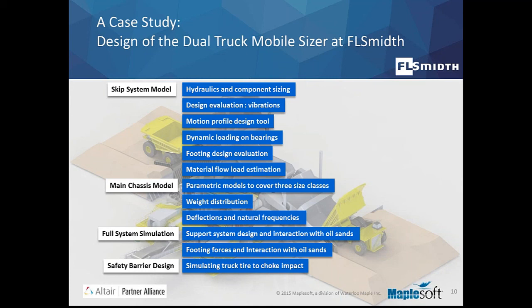This quick calculation that we were able to do was very important to get quick answers to questions before a more elaborate finite element type analysis would come into play. Then we did full system simulation, where we looked at the interaction of the skip loading and moving them at different speeds and different phases, and what it would do to the force that gets transmitted to the ground.